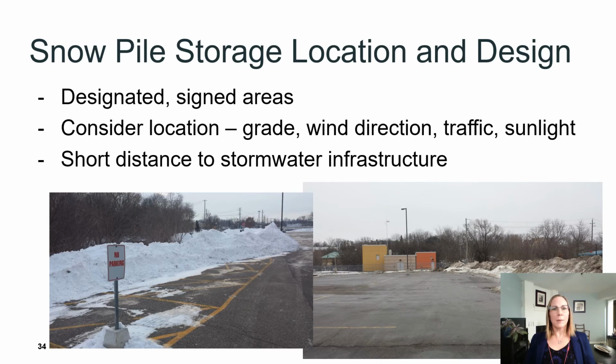Next, we'll look at snowpile storage location and design. So there are a few considerations that we want to look at here. You want to have designated and signed areas, like we're seeing in the photo on the left here, where you've got a sign and your snow pile. You also want to consider the location, so looking at things like grade, wind direction, traffic, and sunlight, and also ensuring that you have a short distance to stormwater infrastructure.